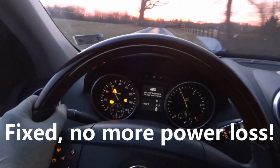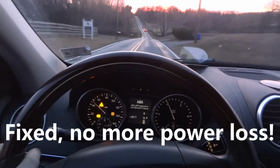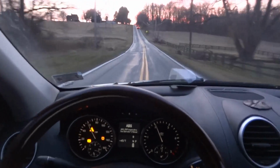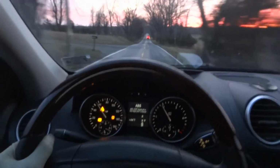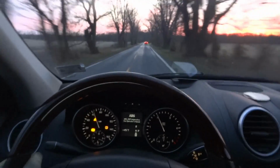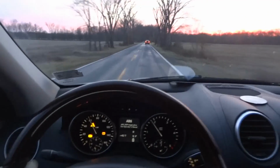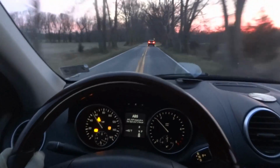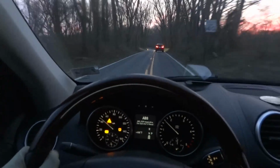So I'm doing about 60 miles per hour right now. You know, before you couldn't drive it this way. You couldn't go up to 60 miles an hour. And when I go faster like this, the engine computer actuates that actuator, the one we just replaced, to move the position of the vanes inside the turbo so that the turbo can spin faster to increase the boost pressure.